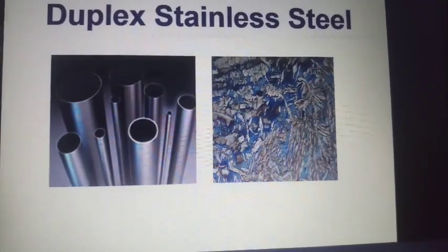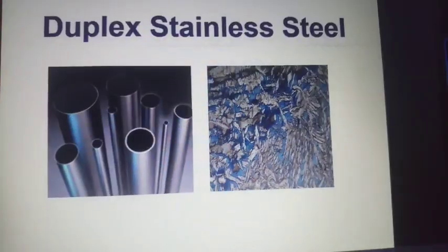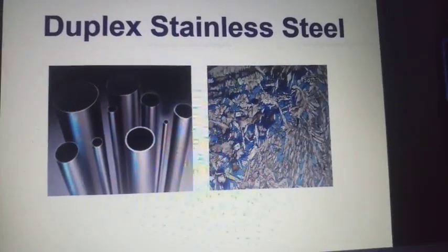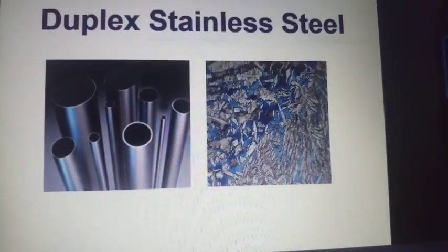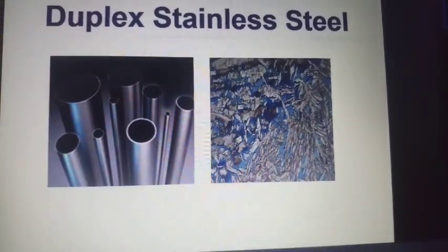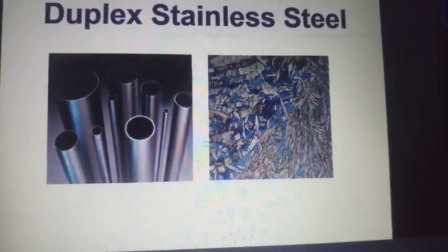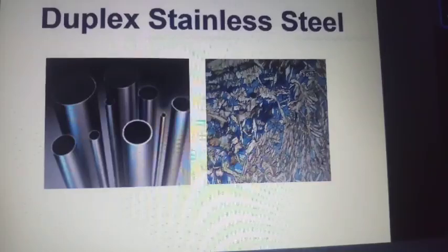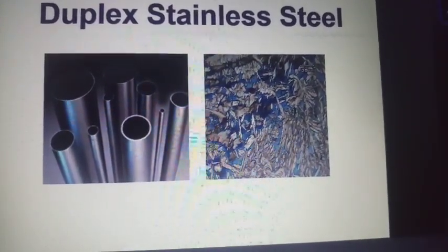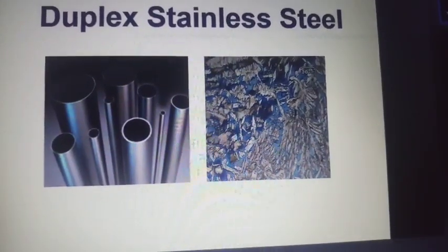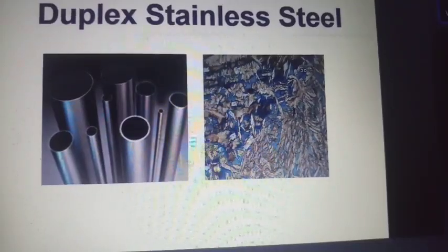How much time will it take to cool down? No, it will cool down faster. I myself have seen this: welding 1 meter, by the time I reached half a meter, the point of starting was already cold. On the 1 meter coupon, when I'm welding with low heat input at room temperature, by the time I cross 300 or 400 millimeters, when I touch the starting point, it is already cooled.